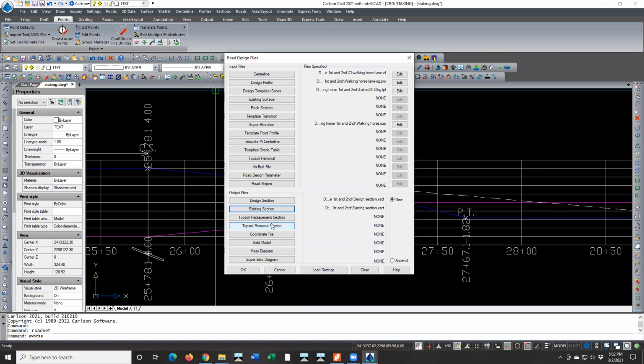Right. Well, yeah, one thing that you can do with those is you could go ahead and build this and output that top final surface, and then you can set those separate individual surfaces from the subgrade. You can go through and find those lines that make the subgrade polylines and use those to create that as a surface.